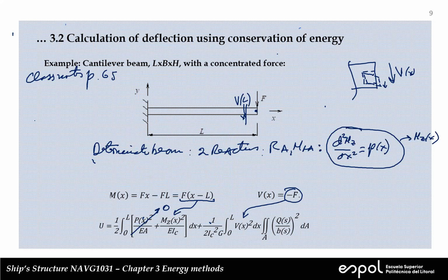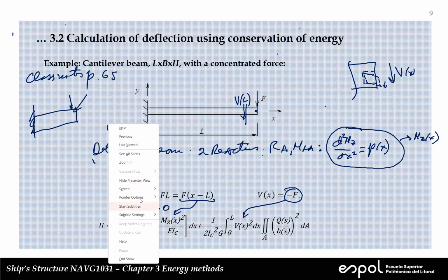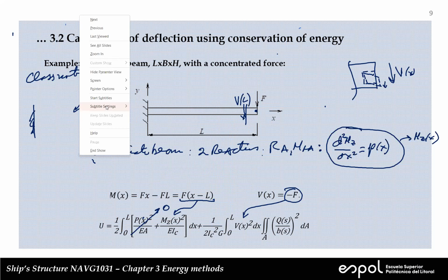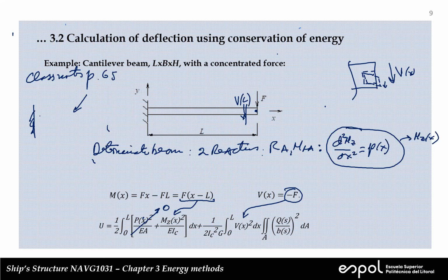Okay, so let's suppose I have a force, the same load. Let's suppose instead of this, I have something like this, so I have a component in the axial direction. You can think that we can analyze this in two steps. In the first step, we're going to have this, and in the second step, we're going to have that. If you have this, you have bending moment. If you have that, you have axial force. Then you simply add them.